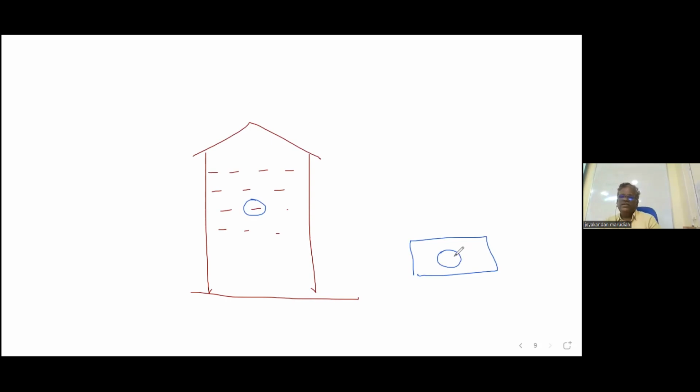Okay, then the nozzle we will prefabricate. So if we take this view, it will be like this. Okay, so this will be a nozzle. Then we will make a weld here, and the weld will be NDT tested. After that, this arrangement will be welded here. We are not making any hole now. After that, we will put a valve above this.